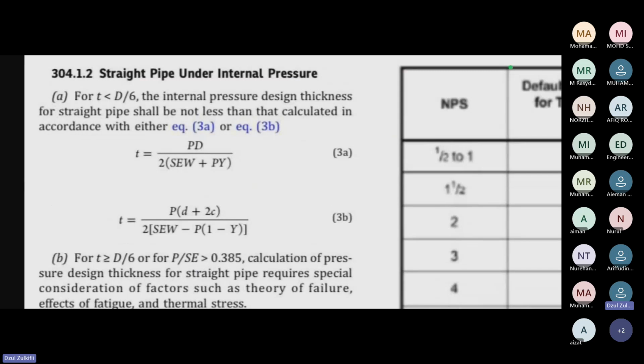You have to go all the way to finite element essentially, because it's an area of high stress concentration, called a discontinuity. So to put it short, the stiffener ring is something important to consider in FFS, but it doesn't tell you how big it needs to be. It's more of a check whether you can do FFS or not, if there is a stiffener ring or not.